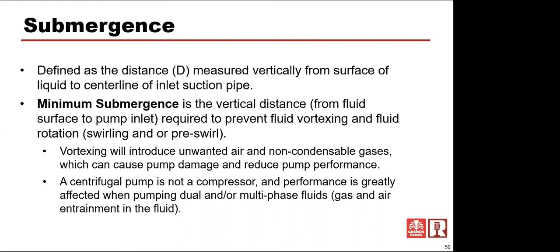We have some pumps that were 95,000 gallons a minute, and we made about a 10-foot diameter intake on those pumps. This was at a floodwater project in the Everglades. And we calculated that we actually wanted to go to about a 12-foot intake given the amount of water over the top of these pumps, or submergence, if you will. So it is very calculable, and it can be proven how much distance you need to prevent that vortex, or that swirling of water or air going down into the pump.